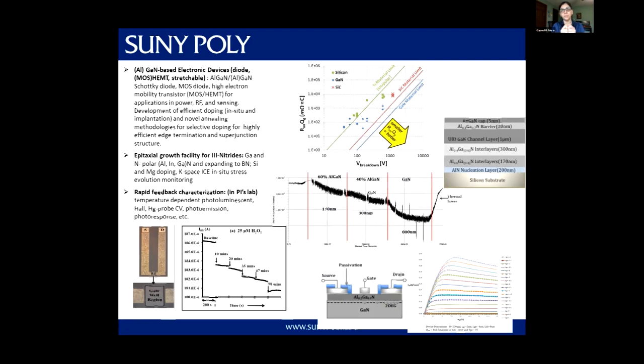So just a little bit about this high electron mobility transistor and why it is so important in gallium nitride. Gallium nitride is a polar material, which means that if you grow it along its C direction, it has polarization. If you put another layer that is compositionally different on top of it, let's say aluminum gallium nitride, now you're putting two polar materials on top of each other whose polarizations are different. Now at the interface, you're going to have another polarization called piezoelectric polarization.